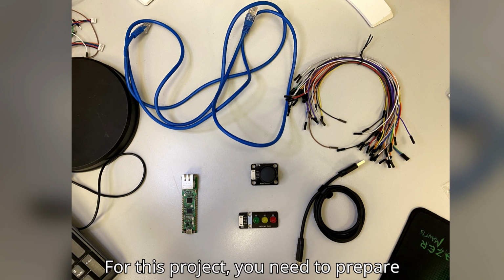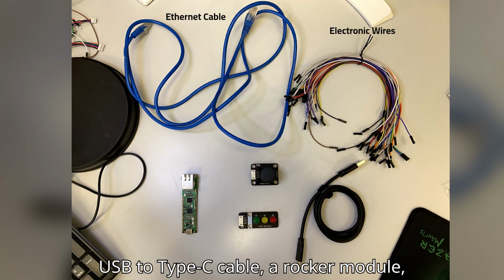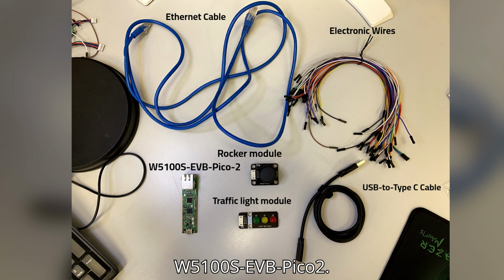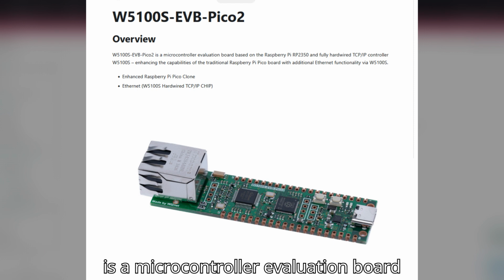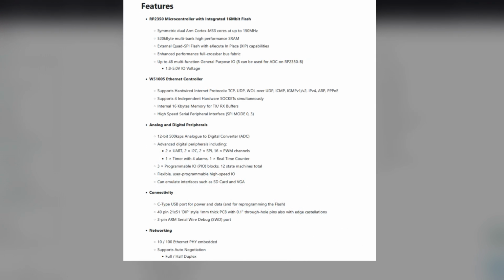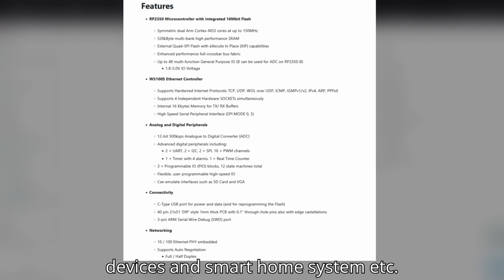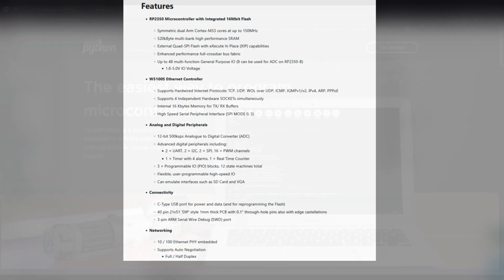For this project, you need to prepare these hardware components, which are an Ethernet cable, some electronic wires, a USB to Type-C cable, a rocker module, a traffic light module, and lastly our W5100S-EVB-Pico 2. The W5100S-EVB-Pico 2 is a microcontroller evaluation board integrating our W5100S chip with the Raspberry Pi RP2350. It is designed to provide Ethernet connection for applications such as IoT devices and smart home systems, etc., with a more simplified process in setting up internet connection.